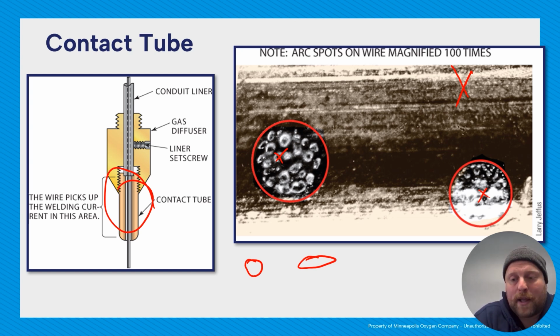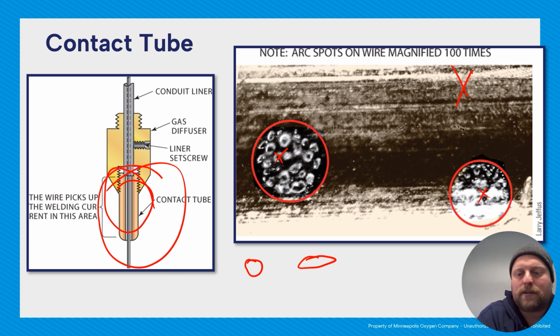And it's designed that way so that it will feed through your liner consistently and wear the entire liner in a consistent way, not just in one place, and so you get consistent contact for electricity in the tip. So that's another thing that can happen. It's probably not going to affect it majorly, but if you allow that spool to unroll at all and then you try to wrap it back up, it can negatively affect the ability and the quality of the weld.